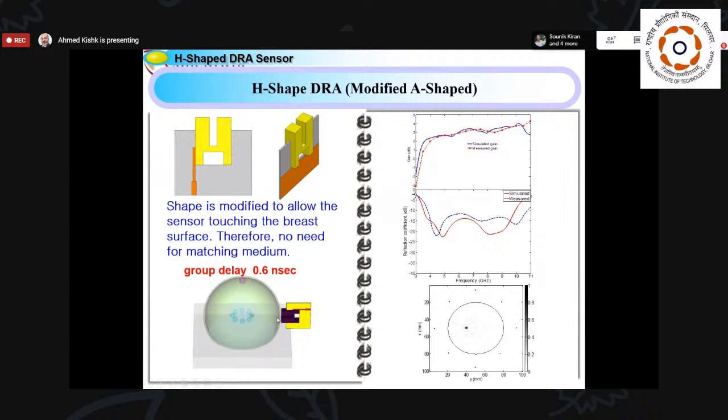And by doing this as well, because our antenna is made from dielectric material, no conductor will be touching the tissue. And of course, the conductor could generate some heat that will make it uncomfortable for the patient. But with a dielectric touching it, this will not cause any harm to the patient. And by doing this, the complete path for the H shape is just the tissue itself. That means we are assured that the signal will be strongly penetrating the tissue.